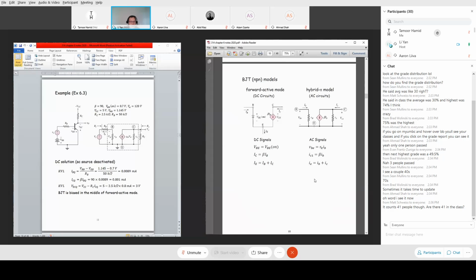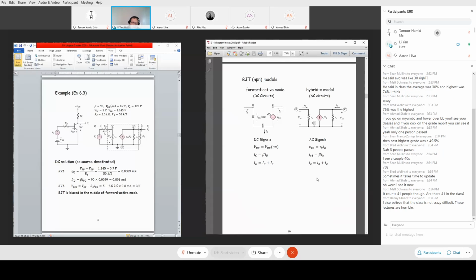Here you can say, well, we made all this effort to derive a model for the DC circuit and a model for the AC circuit. Are there any connections? That's the reason I put these two models to you: to try to make the connections. The connection is that this diode is generally true. Under DC conditions, we approximate the diode as, once it's on, just VBE equal to VBE on, which we call V gamma or VBE on. We neglect that small resistance. So VBE equals VBE on. Under AC conditions, what do we treat this diode as? In AC conditions, we short that V gamma, but retain that resistance R.